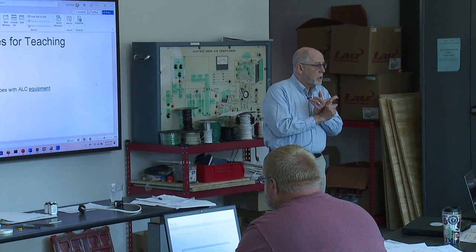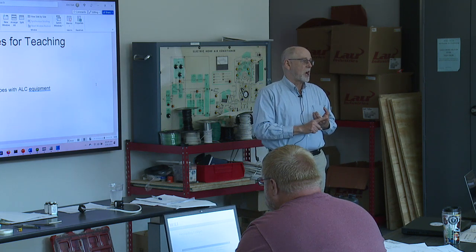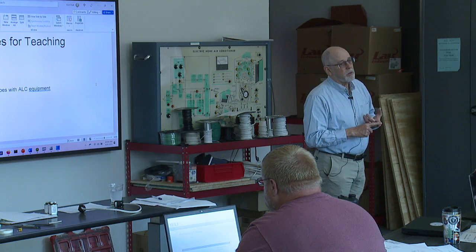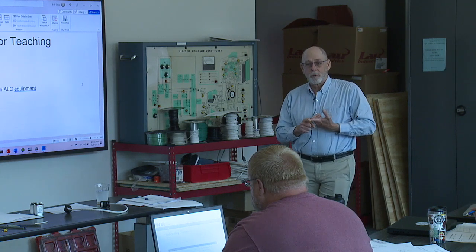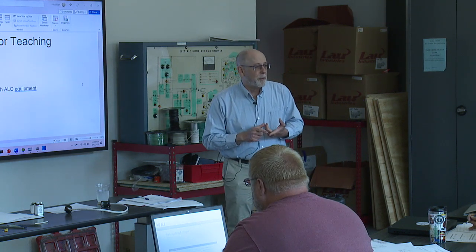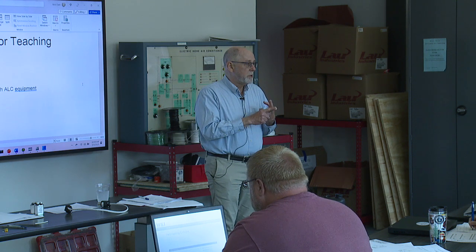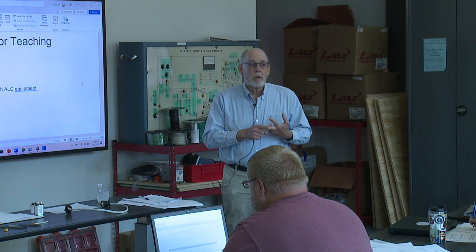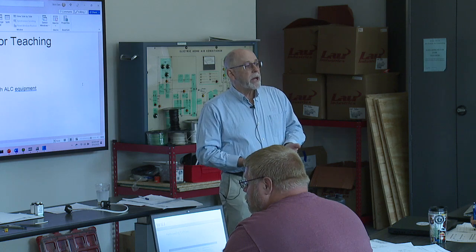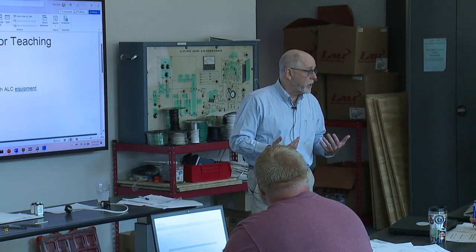wiring. What's Brian Lovell always talk about wiring? One of the most common errors on BAS systems is wiring. So you'll probably find some of that, and I'll blame Keith for those. It's introducing the possibility that maybe we miswired something. You know, maybe we put an AC on DC or DC on AC, or we flipped wires around. So there might be some bad connections that way. There might be bad connections for sensors or whatever.